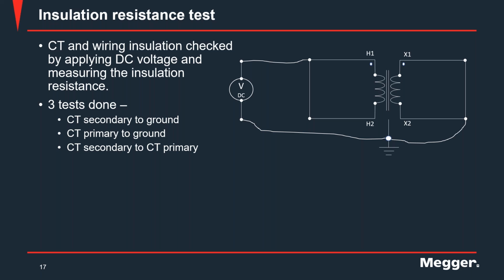The other thing to mention, which is indicated in the question, is that it depends on the scale. Well, as per IEEE, this excitation curve has to be shown in log coordinates, so both axes have to be in logarithmic scale, and the decades have to be squares. I don't know the 1/5 relation. I've never heard of that one, but I just mentioned the two methods that are available. The most common methods are the IEEE and the IEC. I hope that answers the question.